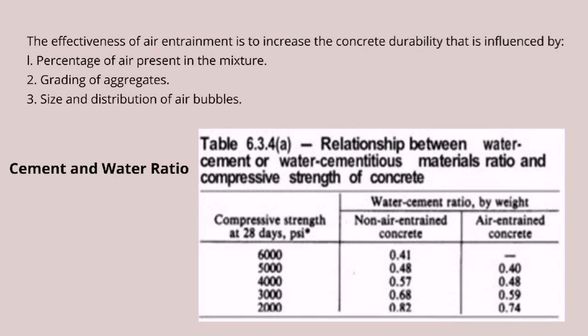Durability therefore is dependent on the water-cement ratio, which should be properly controlled to obtain richness of the paste. AASHTO guide specification for highway construction established the maximum water-cement ratio at 6 gallons per bag of cement on normal condition and 5.5 gallons per bag of cement for severe atmospheric condition.